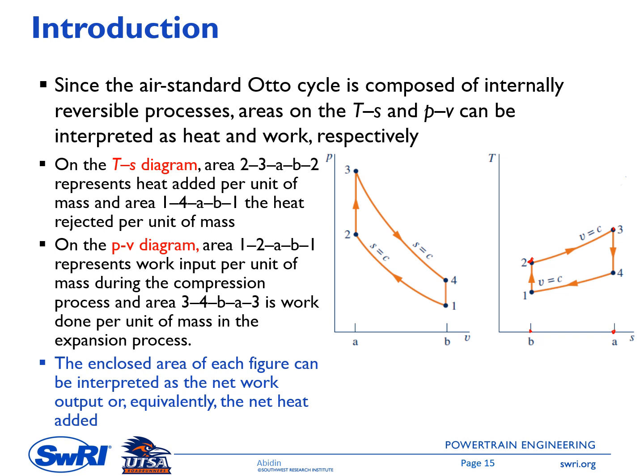added per unit of mass, and then the area surrounded by point 1, point 4 and then A and then B and 1 again. This represents the heat rejected per unit of mass, and the difference of these two heats is the net heat, which equals the net work. And in this TS diagram, it is represented by the area inside the process line.